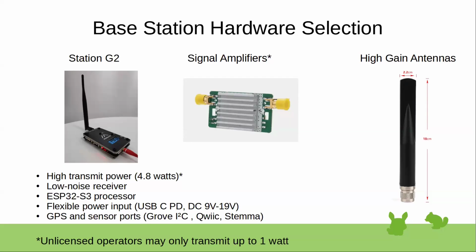So in this 915 megahertz space, there's a lot of products online of antennas, and a lot of them are garbage. So of course you guys are hams, so you can check the SWR of your setups. There are some trusted vendors. Rockland Alpha is one of the really nice antenna vendors for this space, but we've seen some garbage stuff too on Amazon or whatever. So being selective about the hardware is key.